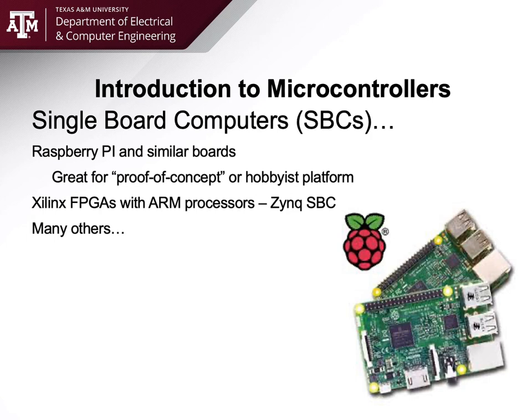In fact, if you go type in single board computer on Google and go to the Wikipedia page, there is a list of all the different types of single board computers out there, and a lot of them are very good and very effective. Some of them have very limited temperature ratings. They're basically rated for the commercial range, which is typically 0 to 70 degrees Celsius. Nothing wrong with that, especially for this class, but if you're designing an industrial-based project, that's not going to work. They're probably also not vibration proof and able to handle harsh environments. So you've got to be very careful where you put a single board computer.